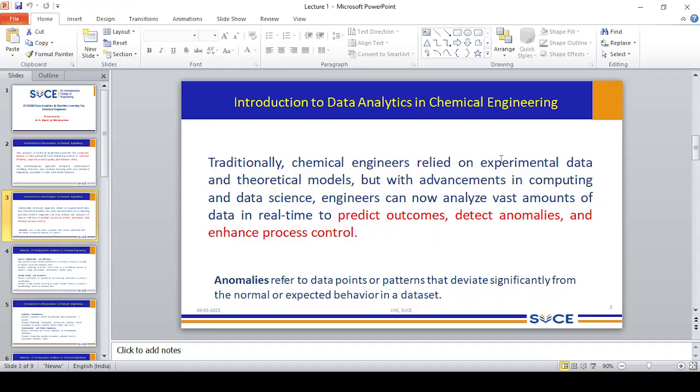So for example, in process control, as a level controller, let's say the level has increased above the marginal height of the column. Let's say it is a water tank filled to a certain level, and the level of the tank supposed to be maintained during the process is only 50% of the height of the tank. So if it is increasing more than 50%, say 55 or 60, obviously what we will do is try to reduce the flow so that the level of the tank will be reduced, right?